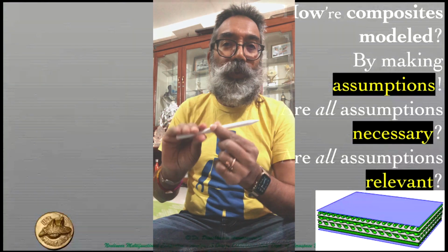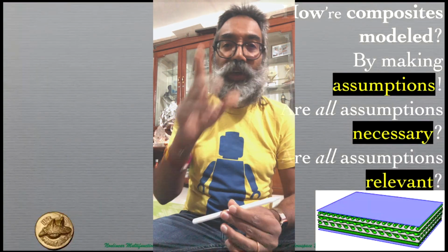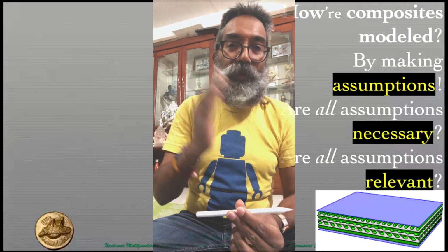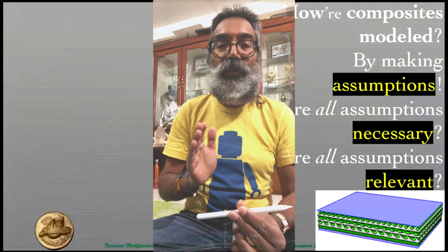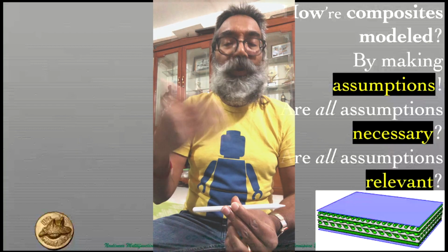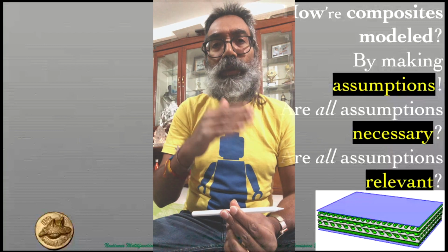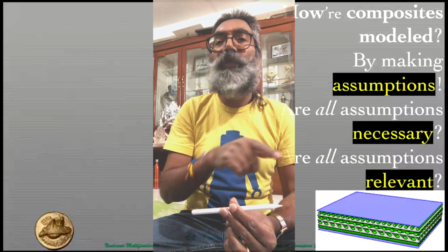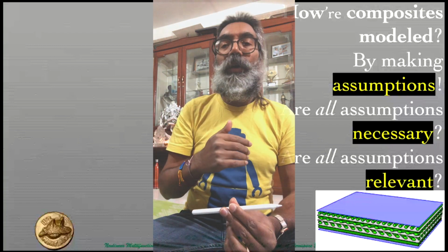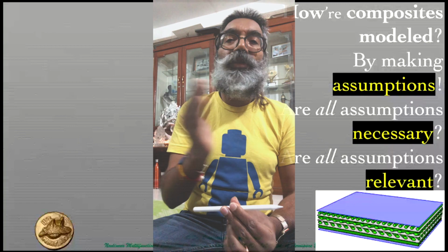So it's good that you brought that cyclic aspect into the picture, because fatigue is typically measured in terms of an SN curve, fatigue performance, and you want a higher strength at any given value of the number of cycles of fatigue that it has gone through. So an SN curve which is higher for one material compared to the other would be preferable as long as all other things are maintained the same. What you're talking about is, yes, there is a strength reduction, but how much strength reduction are you willing to allow? How much, to some small extent, stiffness reduction are you willing to live with? So that's all based on the criteria that you have.